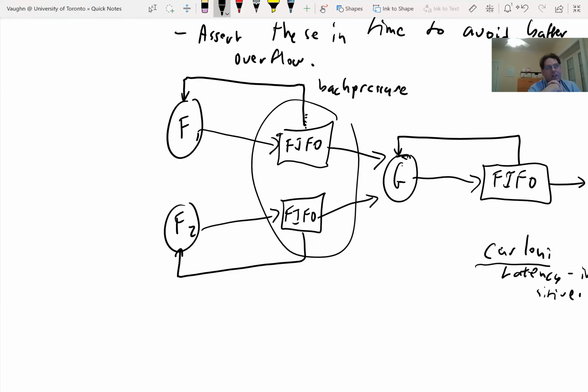Okay, so that was a long meandering answer. I guess the shorter answer is yes. If you just added FIFOs and back pressure and you didn't think about it, you could add deadlock to a circuit. There are some classic papers that show if your original circuit, before you added in extra pipelining, didn't deadlock, then if you add in your extra FIFOs and pipelines following a certain set of rules, you will not deadlock after that.